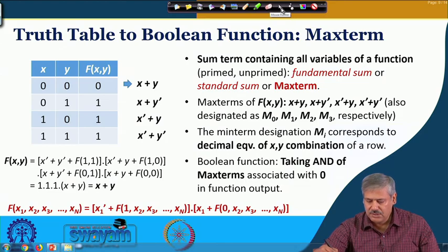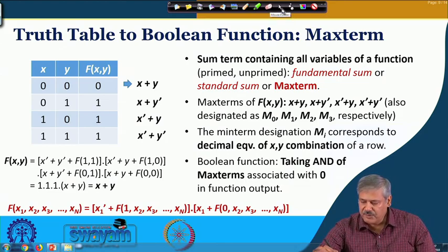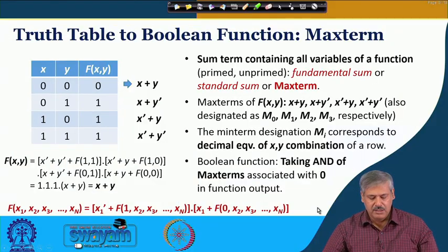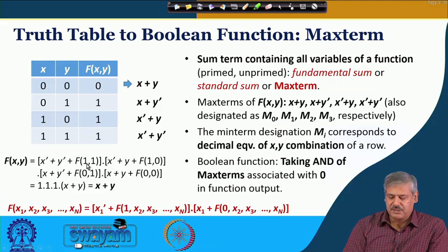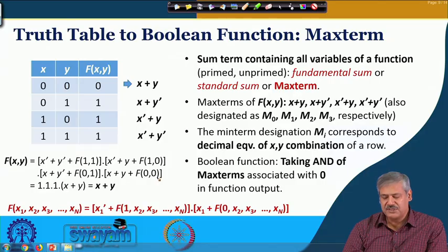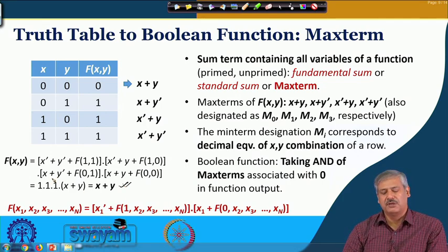So, for this particular truth table, if you keep expanding it, x plus x prime y, right, and then you know all the individual terms and you substitute them over here. We know that f 0 0 was 0 and the rest of the terms were 1 by calculation, and then when you do it, all individual terms will generate 1 and only the last term will generate 0. So, 0 plus x plus y and the rest of the terms are all 1. Okay. So, that gives you x plus y. So, this you are getting from the nested version of Shannon's expansion theorem, this dual version.